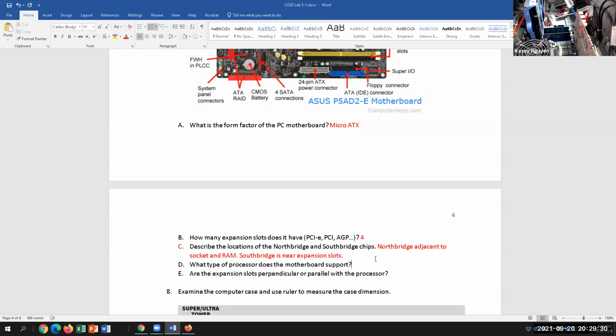Now, when you put it back at home, you want to put thermal paste on it, okay? Because once you remove it, it no longer has that paste to cool. So thermal paste is cheap. You can find it for a few dollars, but not a lot of stores carry it. So you likely have to buy it online, or you can go to Micro Center. I like Arctic Silver, but they have some generic brands that are pretty good. I used to carry some with me, but not today.